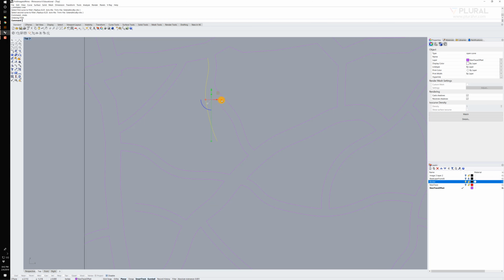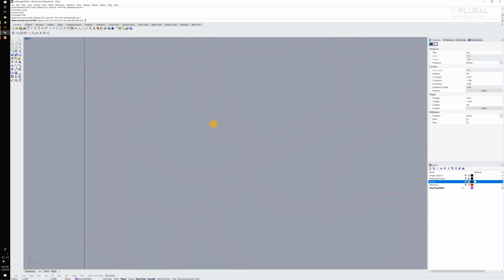I'm going to undo. If I ever fillet this line to this side, you can see it was going to try to put a radius here, but it didn't work because the radius is too large. So I have to make sure I click the end I want to keep filleted. Something like that. And there we go. Oh, here's one more. Let's extend to this line. We'll close that off and we'll trim that out.